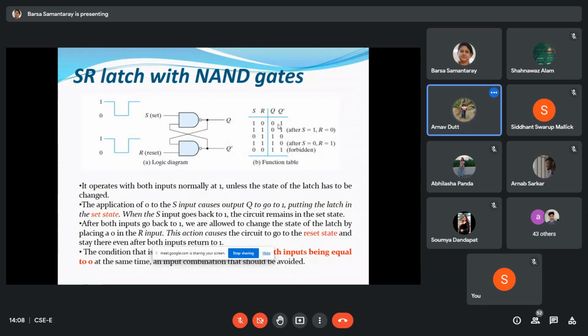Latch is only this set and reset part, and flip-flop is the complete control input part. This is not the proper answer. You can say that latch is SR latch and SR flip-flop is that. But the difference is that a clock signal is included in the case of a flip-flop, which controls the output. And in the SR latch, it is without the clock signal. So what is the difference between this one and which is advantageous? Flip-flop is advantageous over latch.